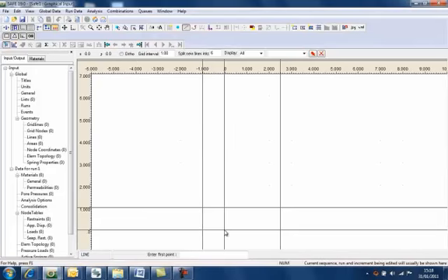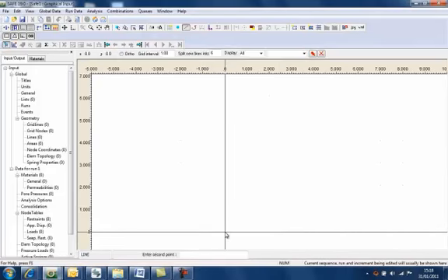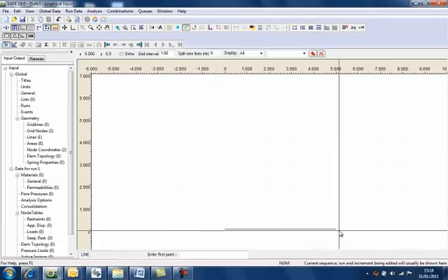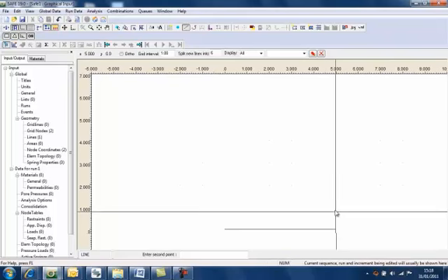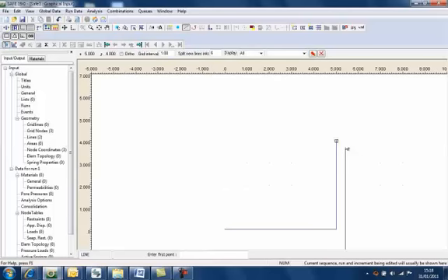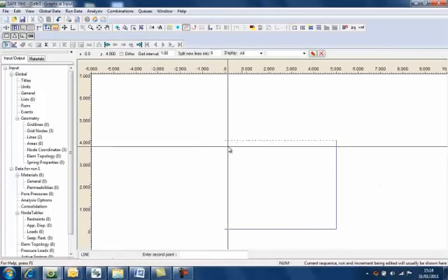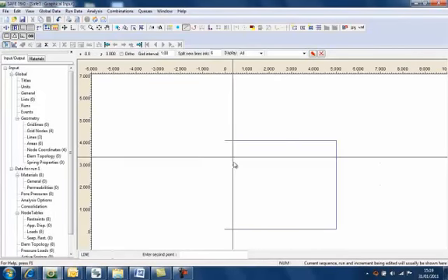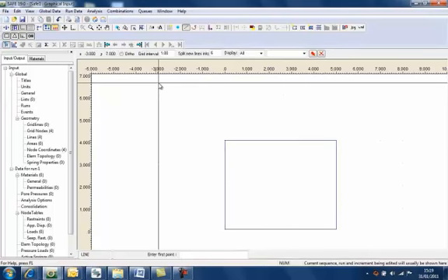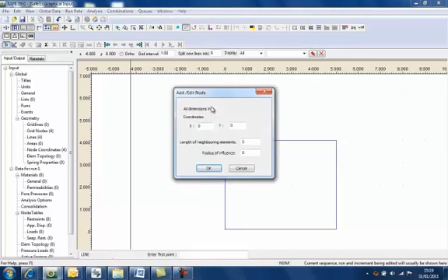You can see it's something very similar to CAD. We've got crosshairs here which help us actually set up the lines. And I'm just here drawing the square. And this square could represent a specific soil layer. It could represent something, for example, where within the square we could draw a retaining wall, or we could apply some loads on top of the square. So once we've assigned properties, as you'll see, we can assign a lot of other things.